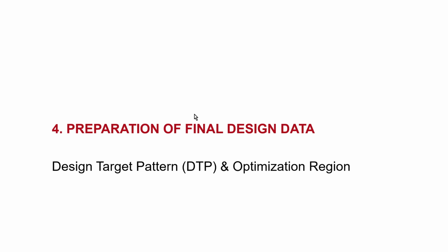Next, we do the preparation of the final design data. What we have not talked about yet was the zeroth order. Typically, when you fabricate an element, there is a height deviation, an etching depth error, a tolerancing for that. In the first example, it was not that important, because if the zeroth order was a little bit higher, maybe it was not that disturbing at first. And secondly, even in our tolerancing simulations, it was within the allowed range.